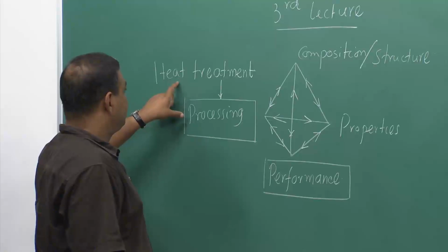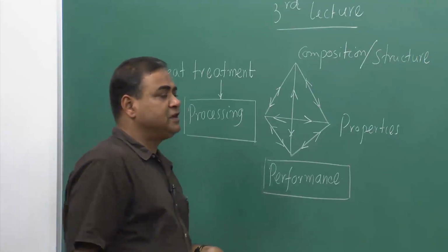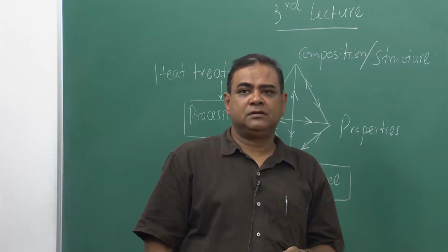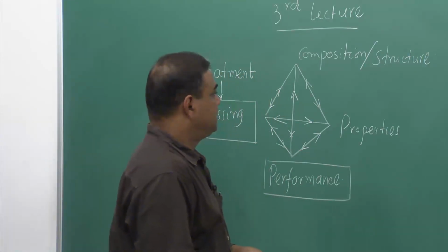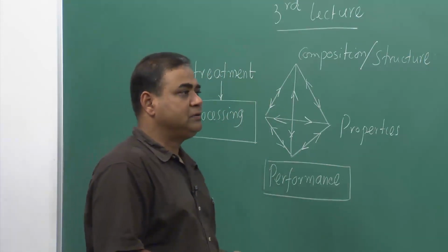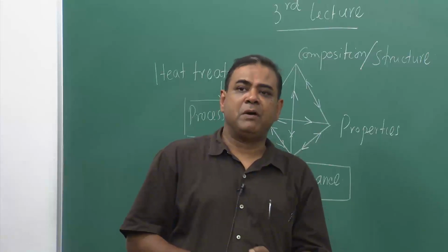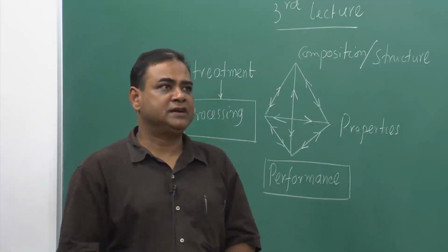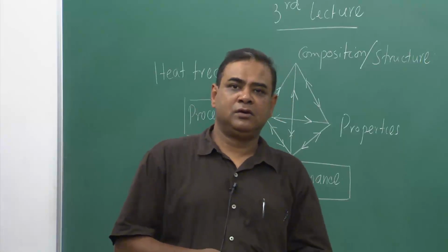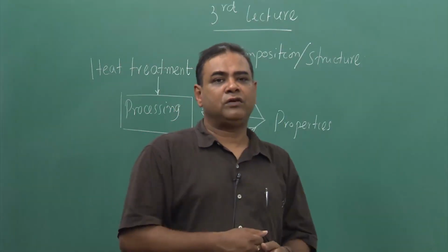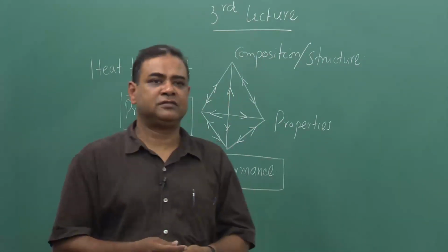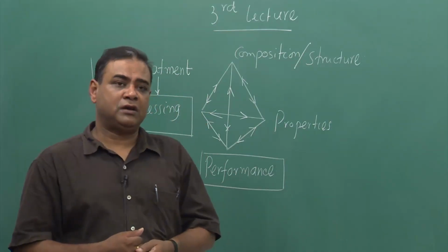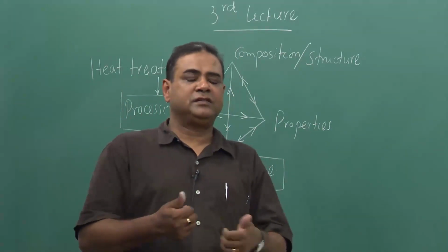And in this processing, we have heat treatment, and heat treatment is nothing but a temperature-time situation. Now, we had an example in the case of mild steel, 0.2% mild steel, where we have seen that if you do furnace cooling with the door of the furnace closed, we have also seen a condition where you put off the furnace and open the door.